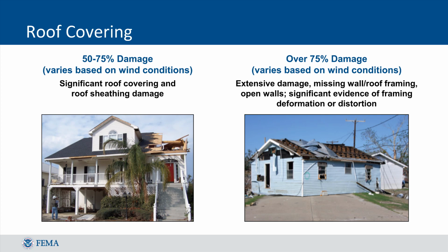Damage of 75% or more to the roof entails significant loss of the entire roof element. Generally, in these cases, most of the roof is gone, and there are wide openings on top of the structure that expose the interior to the elements. If there are parts of the roof still remaining, they are small and most likely do little to protect the structure itself.